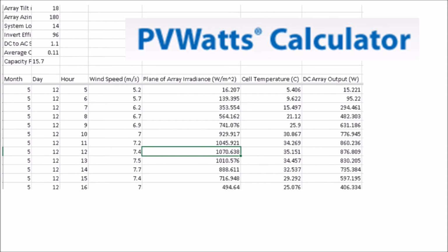So calculating solar performance isn't as simple as taking the size of the solar array, multiplying by the hours of daylight, and then getting the amount of energy the solar array will produce from it. The wattage rating on the module assumes that 1 hour of daylight is 1,000 watts per meter squared, but actual daylight hours rarely get up to that amount of sunlight shining directly on the solar panel. So a software like PV Watts is needed in order to estimate solar production. It's easy to use and covered in some of our other classes.